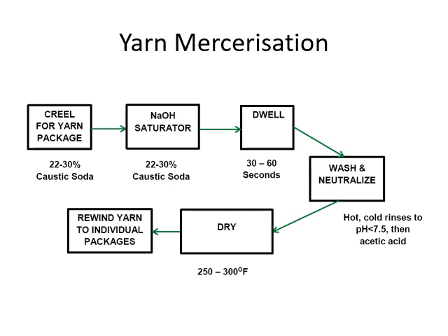Yarn mercerization is only possible with plied yarns due to the high tensions used to create lustre. The best results are obtained when the yarns are singed prior to mercerization. These yarns can be dyed prior to knitting or dyed after knitting in fabric or garment form.